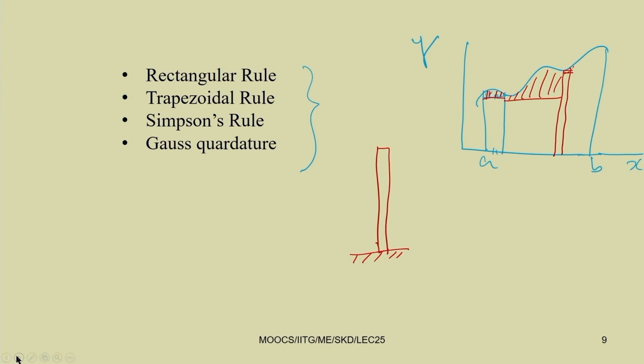In this base excited cantilever beam, you have seen the spatio-temporal equation of motion. For example, the first two terms, if you want to write for the Euler-Bernoulli beam equation, you have E I del fourth W by del x fourth plus rho A del square W by del t square. These other nonlinear terms are also present when we consider the system to be nonlinear.